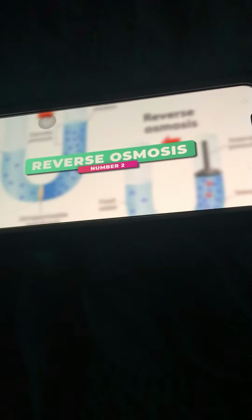The electrodialysis reversal process works like the electrodialysis process. The only difference is that in the reverse process, the polarity or charge of the electrodes is periodically switched. This backflow of ions helps remove floc and other membrane debris, thereby extending system life. Number 2. Reverse osmosis.